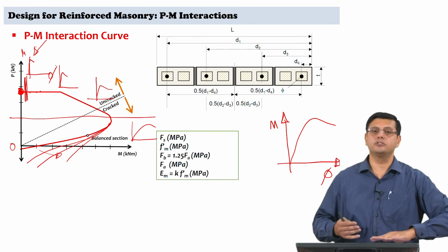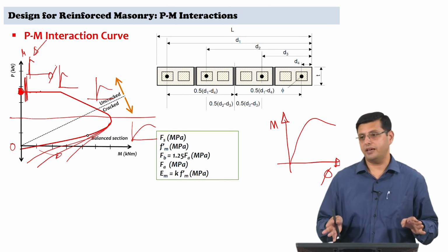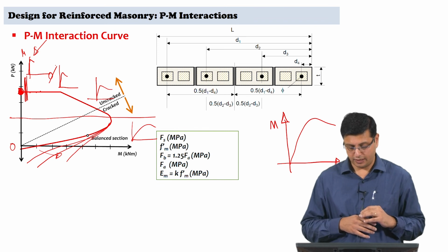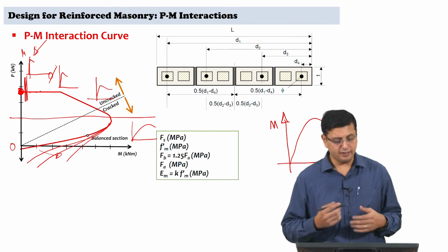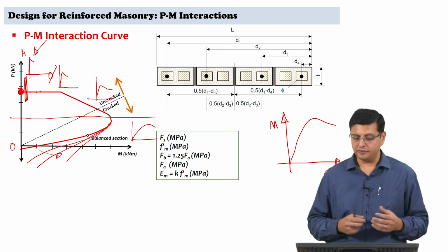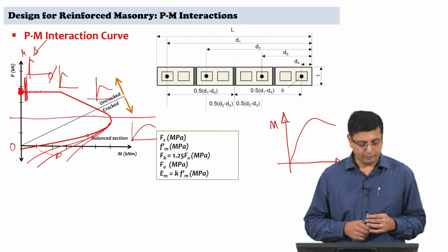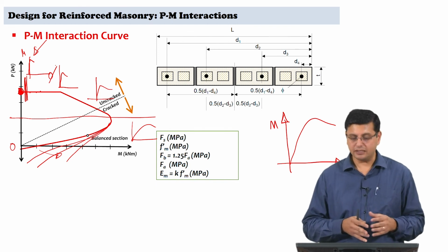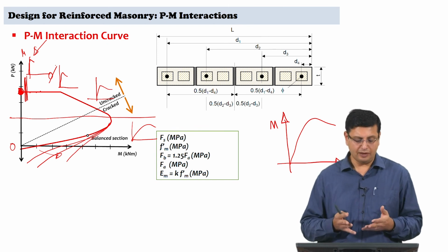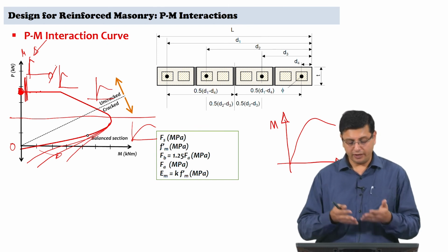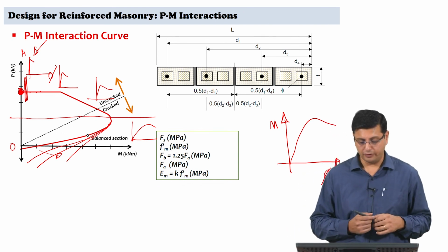Whereas here you have a structural solution that gives you the possibility of achieving good deformation behavior as far as earthquake forces are concerned. So, this is something that you will see is discussed quite extensively in the literature on seismic behavior of reinforced masonry, and I wanted to close the PM interaction discussion with this particular aspect. So, you value the PM interaction that you are doing as a demonstration of good ductile behavior of reinforced masonry itself.